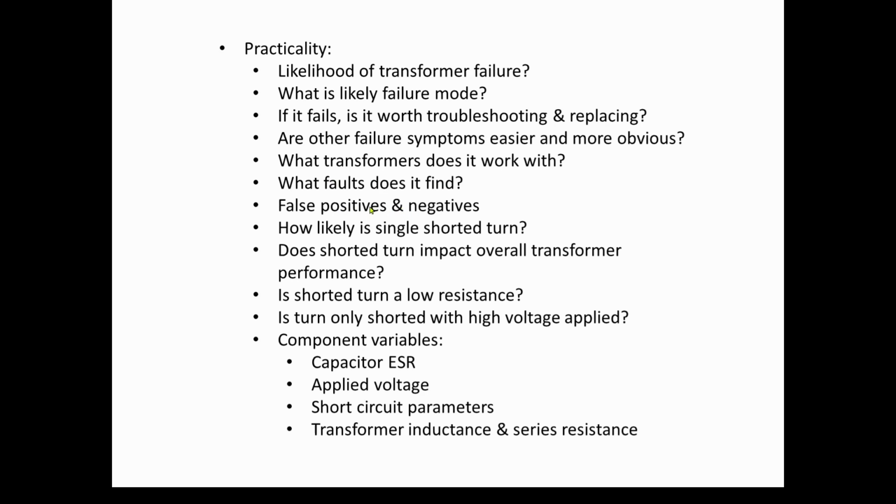And you also have to worry about false positives and negatives. Are you going to have a good transformer that you put in the ring tester, and because of these other factors, it maybe says that it's a bad transformer, when in fact it's good? So you really have to investigate this, what it works with, and what is really a good transformer. How many rings for a good transformer and how many rings for a bad transformer.